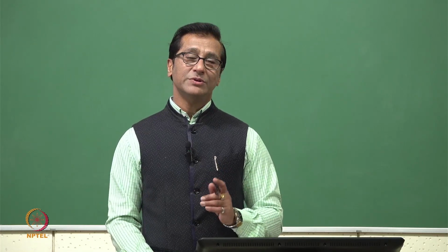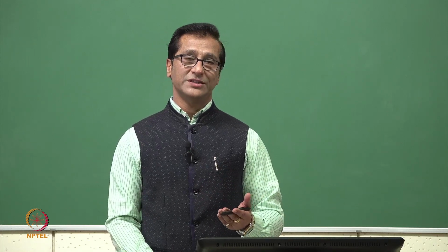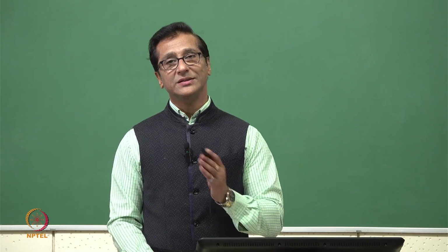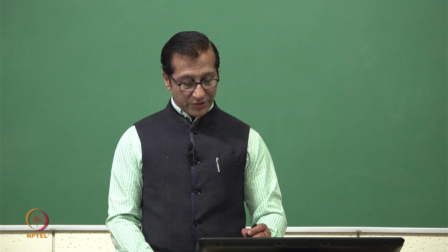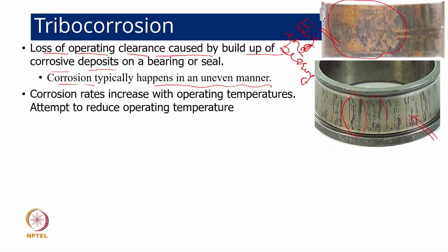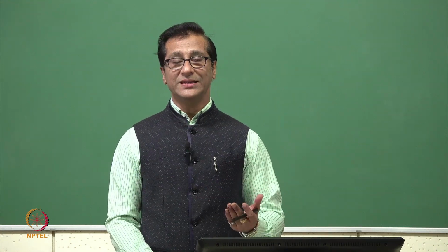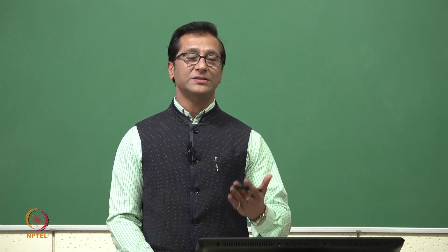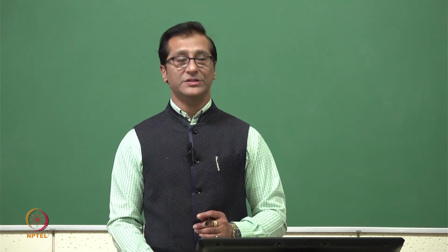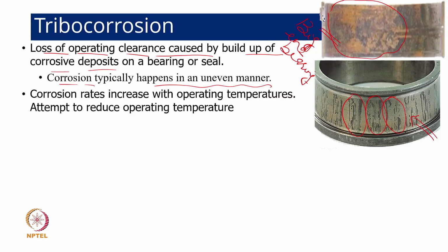So this corrosion brings more and more non-uniformity on the surfaces, causing more and more problems, and increases the surface roughness also. Now here in this patch, you can see the stationary roller element bearing and patch are formed. After that, naturally the vibration level will increase. With the increase in vibration level, naturally impact will increase and the bearing life will come down in this manner. So that's why we are saying that corrosion creates more problems in tribology in this case.